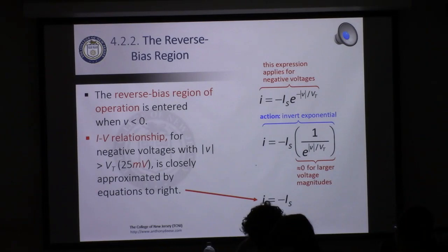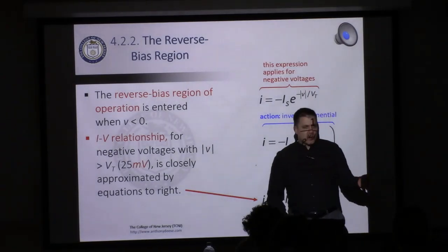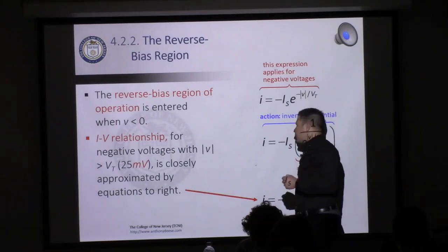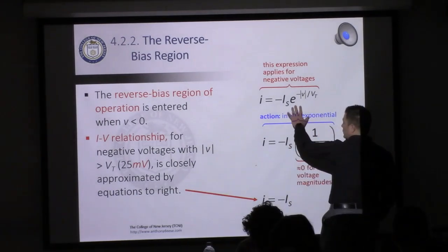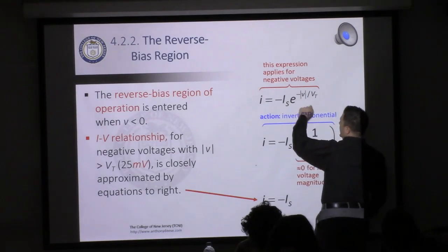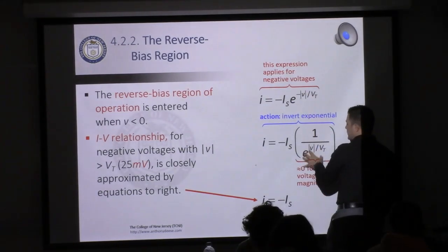All right. So we have danced around the topic of the reverse bias region. We haven't really addressed it head on. As we know, the reverse bias region of operation is when the voltage across the diode is negative and it blocks. So we can use our same exponential equation, and when V becomes negative, this component here will get very small.